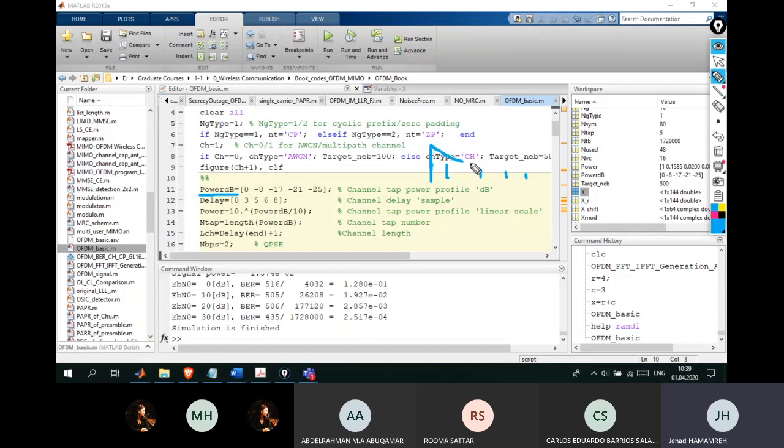So this is basically our channel. When you draw it, it's kind of exponentially decaying. So this is coming direct line of sight maybe, or this comes after reflecting off a building, maybe a tree, the floor, a mountain. Each one gives us a copy of the signal, another version of the signal, and this is how the channel behaves. And here it gives us the delay. This is the power value. Now you might say this is 0. How come you are putting a certain amplitude for 0? 0 means no power. No, I tell you this is 0 in dB.